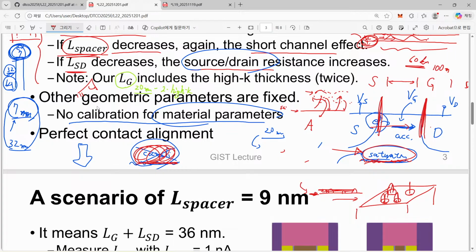But unfortunately, it's not so. It really introduces a huge impact in our calculated result. Without this kind of velocity saturation effect, we never achieve the proper level of current value. The thing we have to do is careful calibration of saturation velocity. So that is the problem.